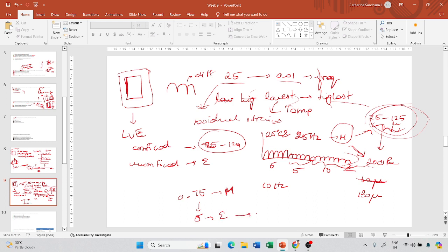If it is within the limit, 75 to 125, it will keep the stress value as such. If not, it will vary the stress value, because from the stress and strain in the seeding cycle, it would have found out the actual modulus of the material at 10 hertz, and then this process keeps repeating.